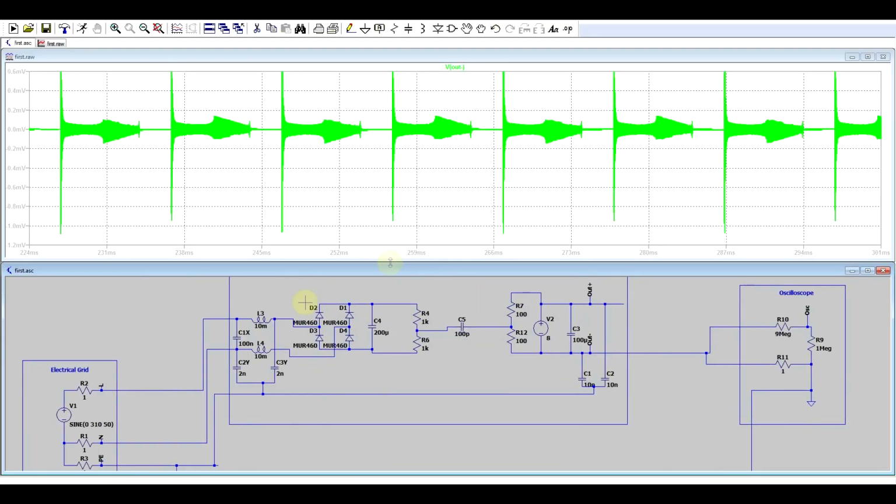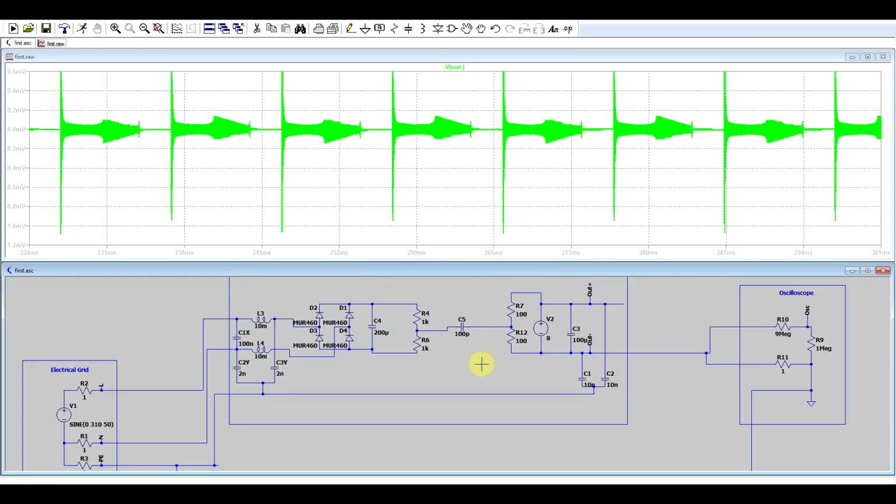So the thing that we're missing at the moment is the actual flyback supply. Until now, I just simulated the power supply as a load on the input side and as a generator on the output side. I didn't really simulate the flyback supply itself. And for that, I will make a completely different simulation, because of the way it slows down the simulation if I simulate everything starting from the electrical grid. The important thing that we've learned from this part is that we have this stray capacitance, and this is something that we need to include in our next simulation.